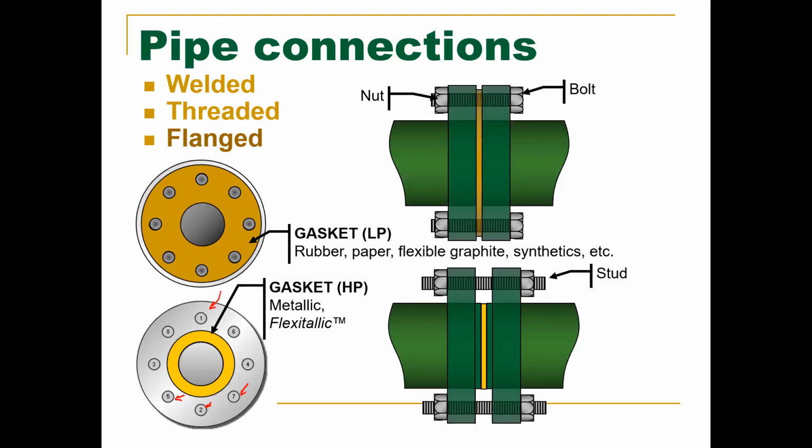Now, one last tidbit of information: paper. For you mates out there, if you ever get the question from your engineer asking for chart paper, this is why. Chart paper makes excellent gasket material. It works fantastically well. It has some sort of fibers in there, some string material, and it holds together perfectly. It's just thick enough to be used as a gasket.